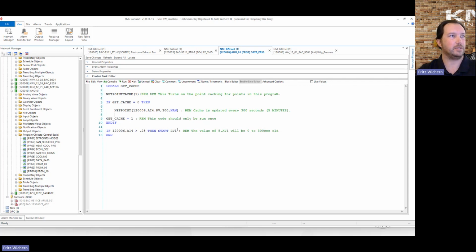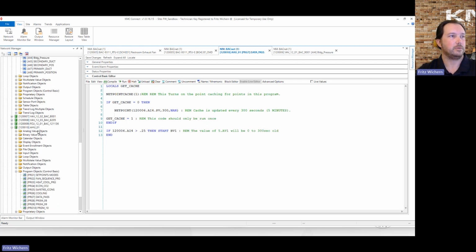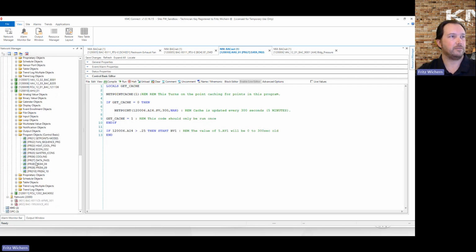Lots of options there, but the point being, we took a canned VAV application and used an open input on that controller. So there's functionality and flexibility that you can use our canned applications to build onto to save you some time. You're trying to make the best out of what's there.